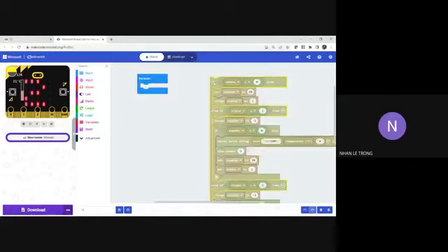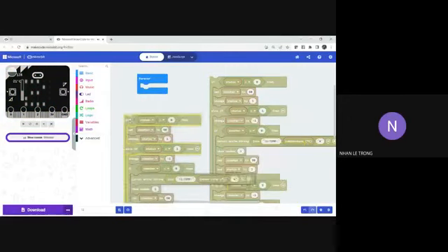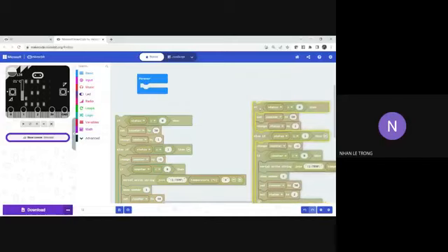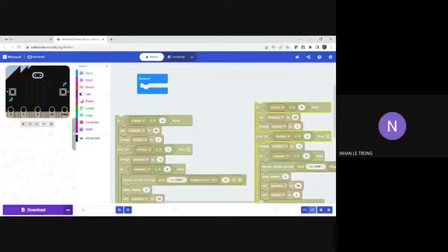Imagine you have another state machine for the LED, like this one. You put everything in the forever, and at a given time, one state of the LED machine is executed, and one state of the sensor machine is executed. And this is the principle of the operating system. This is the round robin operating system.